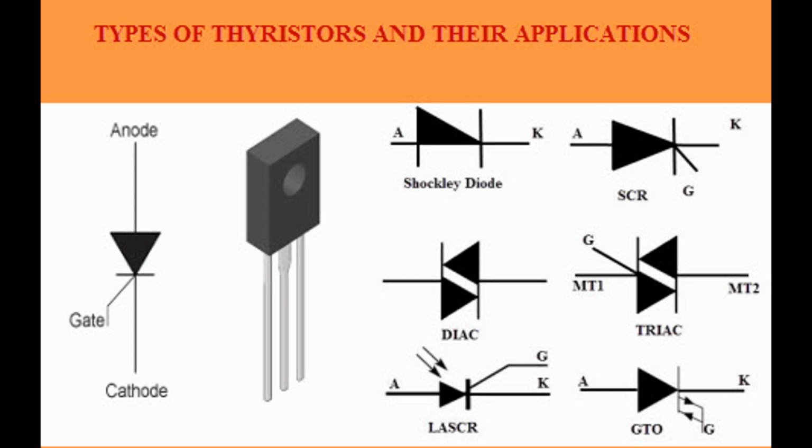High power handling. Can manage large currents and voltages, making them suitable for high-power applications. Simplified control. Provides more straightforward control compared to using separate circuits for turning off SCRs. Limitations. Gate drive complexity. Requires a complex gate drive circuit to supply the necessary turn-on and turn-off currents. Heat management. Generates more heat during switching, requiring efficient cooling solutions.